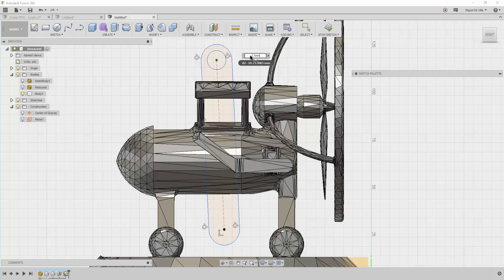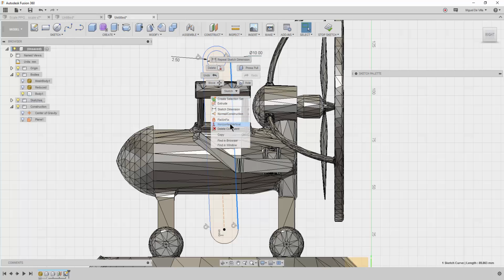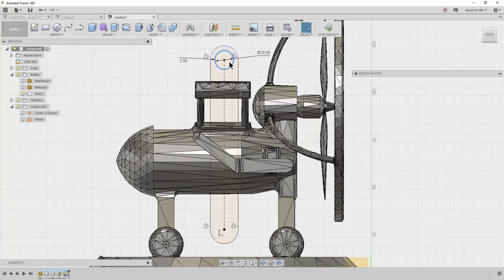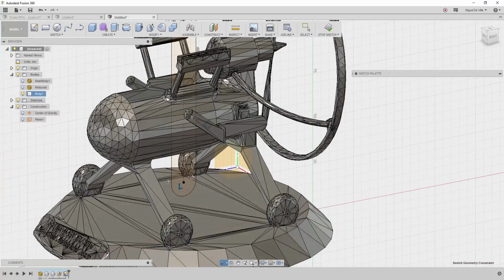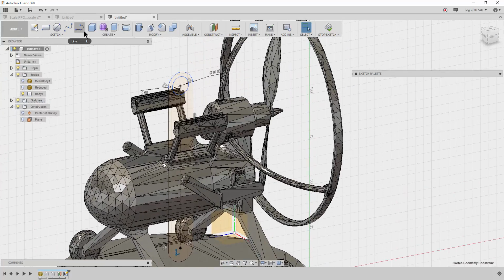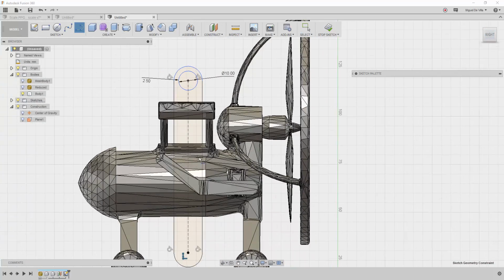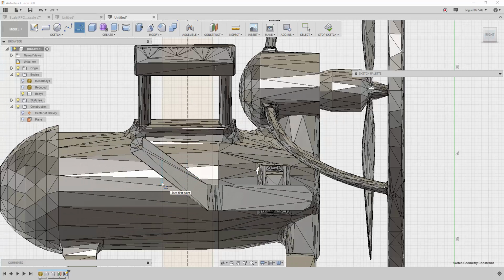Let's say 2.5 meters. Whatever is good. This isn't a properly scaled model yet, and I will do that later in my slicer. Make this vertical so that we can get a nice, tall, straight tower. And notice that it is now coincident with our projection of the center of mass, so that when I convert this back into a mesh, it'll be in the right place.